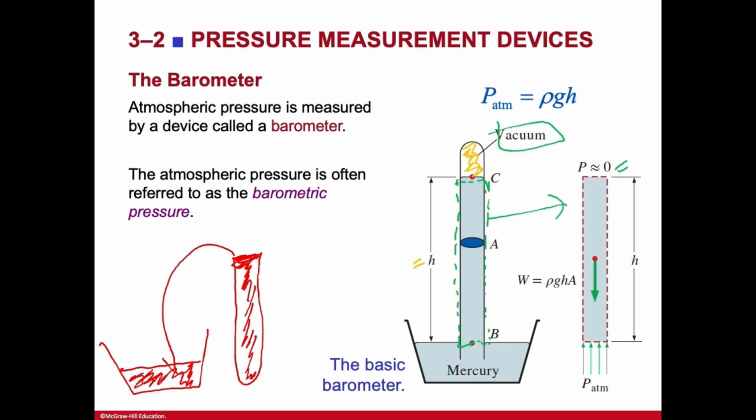The pressure at point B is at the same level as this free surface, and you have the same continuous fluid and the fluid is static. So the pressure at point B will be the same as the pressure at this free surface, which is nothing but atmospheric pressure because it's exposed to the atmosphere. Essentially, the whole atmosphere of the earth is pushing down on that free surface.